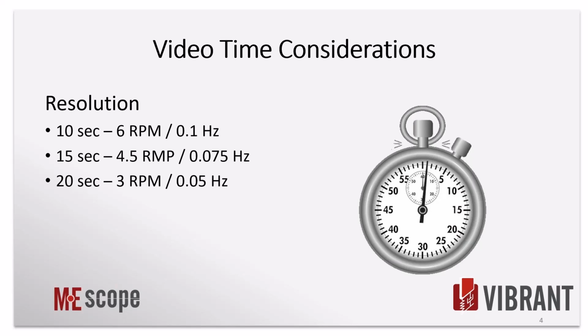So if you really need to do an in-depth analysis, and if you have closely coupled modes or things like that where you need great resolution to start picking things out, the longer the video the better. Processing obviously takes longer with a longer video. That's just how it works with computers, but you will get that increased resolution. No different than you would use an accelerometer. Conceptually, it's exactly the same.